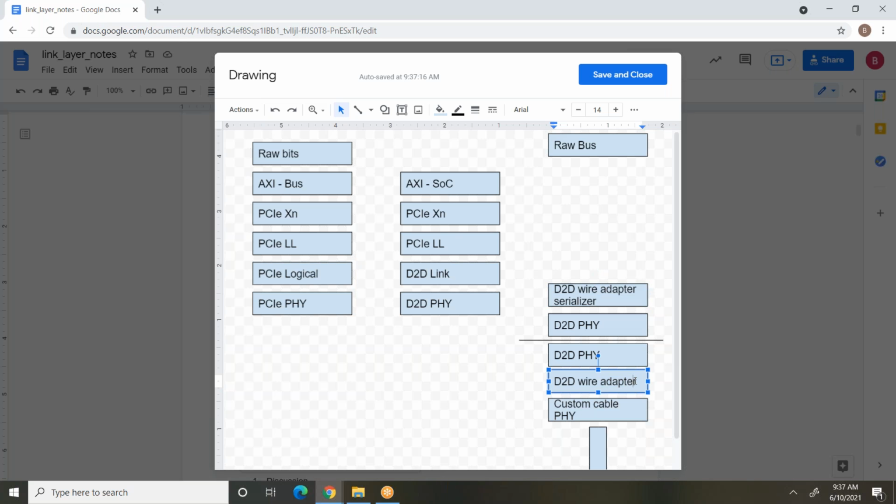So there is a service there. If you're multiplexing a wide interface down to a narrow interface, you can provide a sort of unscrambling, what's the word, shuffle service. Shuffle, yeah. So you could define a training pattern. The nice thing about die-to-die chiplet environments is it's not plug and play.